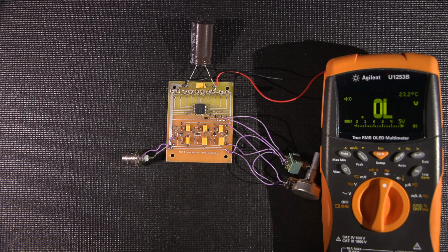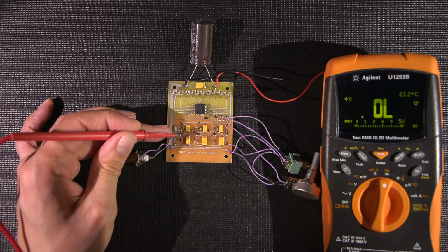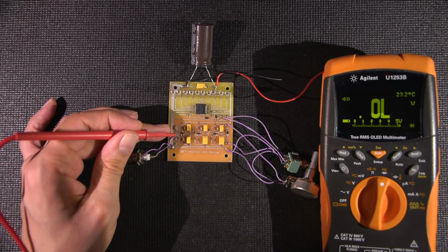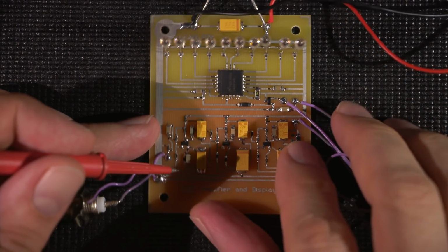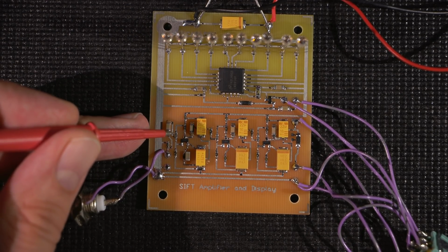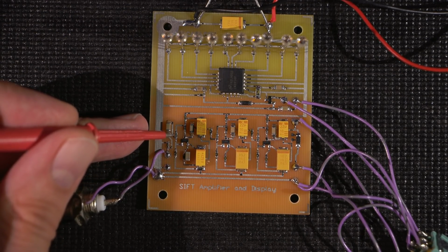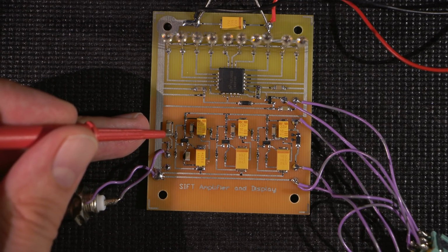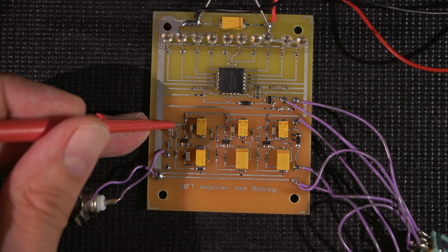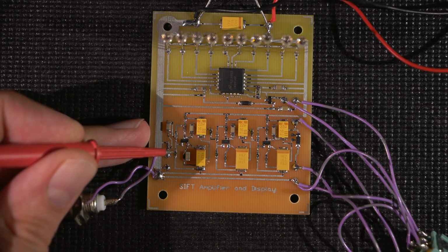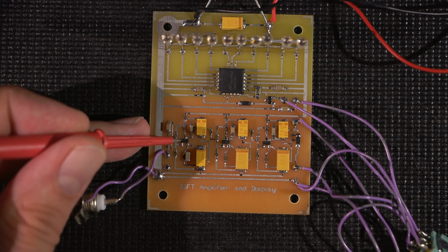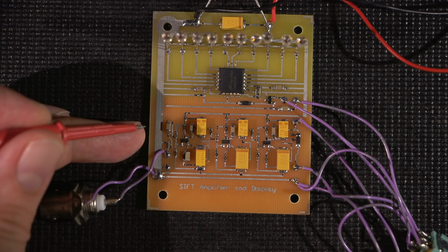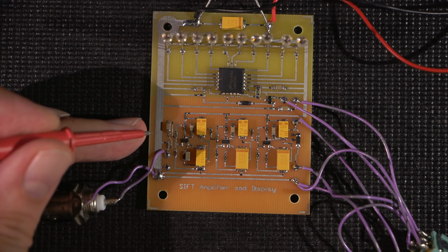So now that we know that we have NPN transistors in here, we know that the signal is being fed into the base. I'll just zoom in here a little bit again. Get this out of the way. So we now know that the signal is going to be fed into the base. We can see that we have 2 resistors here, so that would be the biasing, right? If you look at the schematic, you'll see a resistor that runs up here, just above a resistor to the collector, and you'll see a resistor running down here to the negative. This is what's setting the bias for this transistor to get it right to that point to where it's going to be useful in an audio circuit.